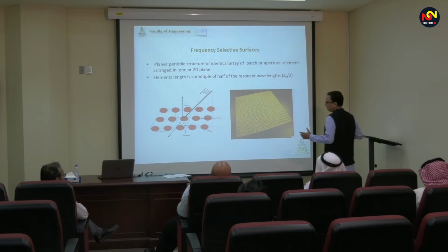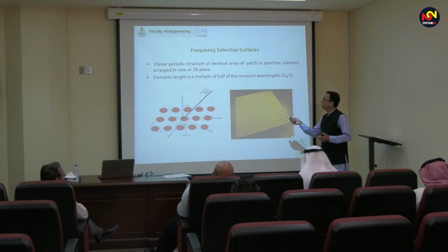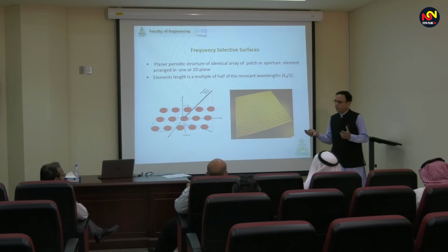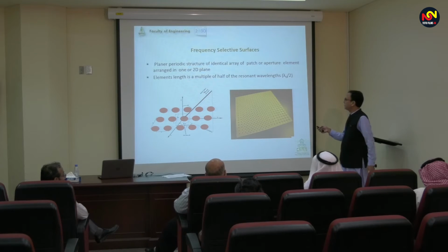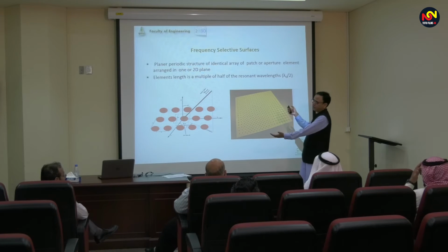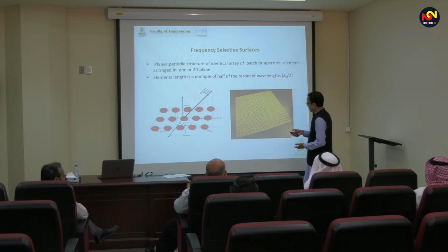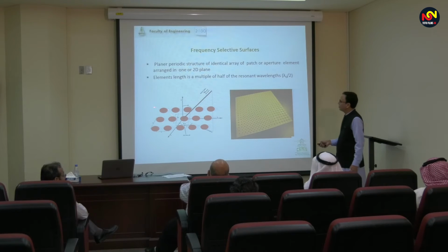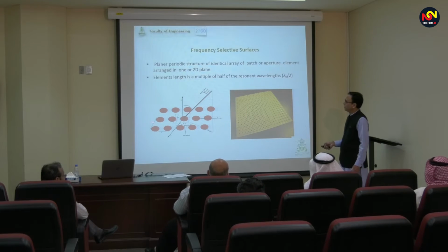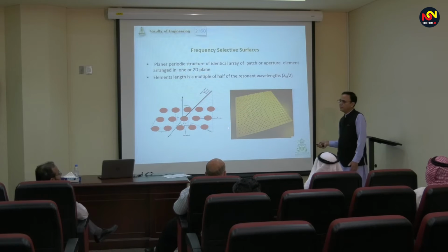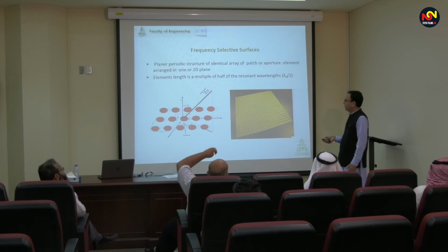So, it is stopping all the signal by 30 dB, which is a big loss. This problem of the signal going through, we can solve through a technology called frequency selective surface. What are frequency selective surfaces? They are actually like a filter, but in space, not in the circuit, and they are basically periodic structures put in periodic x and y directions. Like here you can see there is a periodic structure, these are cross dipoles, this is basically an FSS structure, and according to the frequency which we design, it either passes or stops.